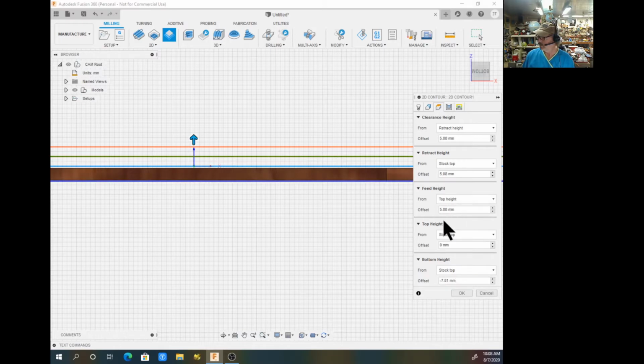Okay, so my top is going to be 0. I'm going to leave it at that. The retract height and clear height, I leave them up pretty high anyway, what it recommends. But when you zero it in Maslow, then it'll move itself to transfer. So I'm happy with that. This is one of the reasons why I'm not exactly down on 0 at the very bottom. This is why I like the tabs a little bit higher, so I'm not completely cutting through them.